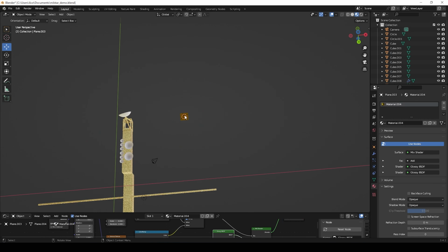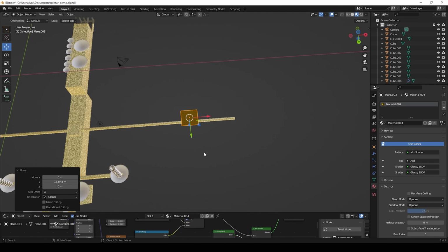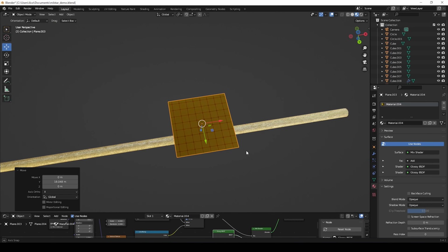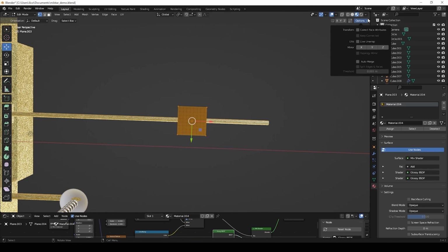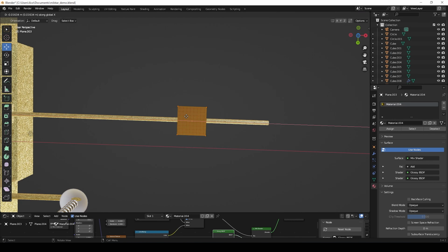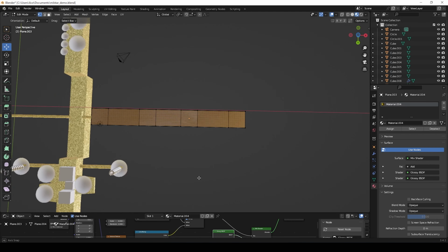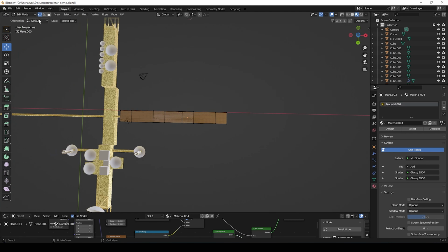So what I want to do is move that solar panel texture down underneath the solar panel struts. I'm going to go into edit mode. I'm going to go to options and make sure I do correct face attributes. This is part of why I built out the material first, so that when I stretch this object out, it's going to maintain the pattern that we built out. So we'll click all, click E for extrude, hit X, and we're just going to extend out our solar arrays. Okay, so now we've got the length of the solar panel set up.